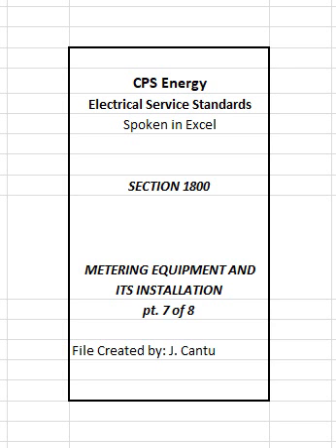Service shall be capable of accepting up to 6 individual meter loops. Auxiliary gutter shall be sized as per NEC but in no case be less than 12 inches high by 10 inches deep by 6 feet long, refer to figure 1901, note. Customer will be required to furnish and install a step bus auxiliary gutter where service lateral conductors or any one set of service entrance conductors are sized larger than 2 to 350 kcmil conductors per phase.